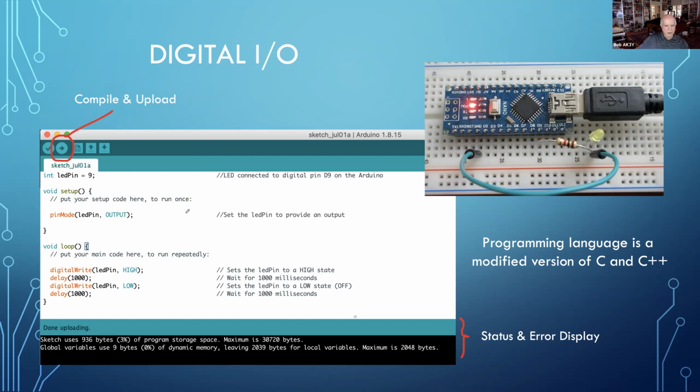This is really not much of a C programming language here that you see, but it can already do some interesting things. So in this case, I'm going to connect an external LED light. This could also be an external transistor switch, or an external relay through a transistor driver, anything that would accept a digital input output. With a digital control, I'm going to turn this LED on and off in some fashion. I'm going to mimic what pin 13 did when I booted the microprocessor for the very first time.